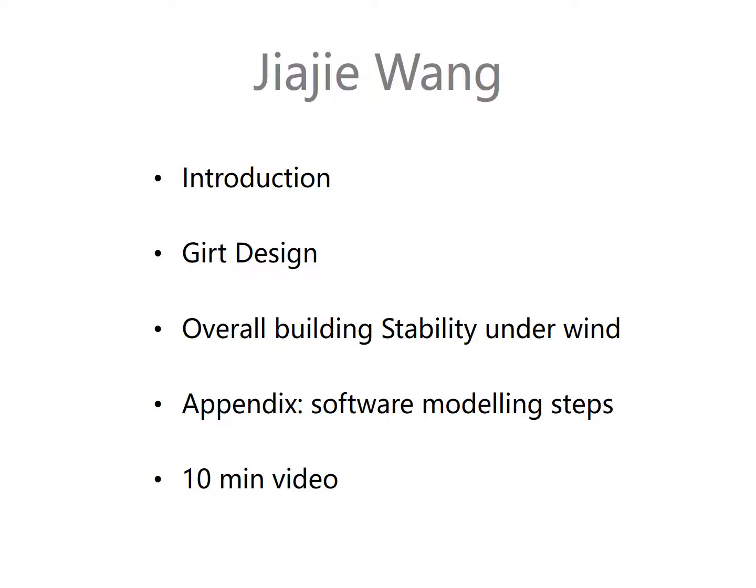The purlin spacing is an important value that influences many things, such as dead load, live load, and wind load. Different span and height of purlin and the wind terrain category also affect the result of design. The girt part is similar to purlin design. The dead load and live load of girt are the same as purlin. However, the wind load of girt is different from purlin because the area of roof surface and wall surface are different.